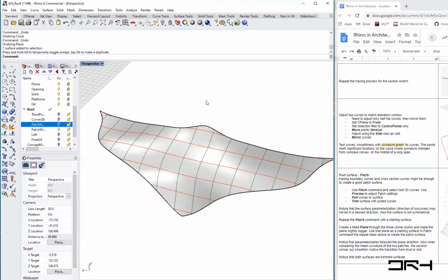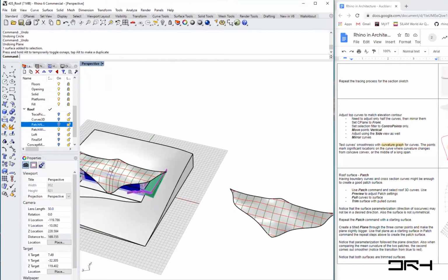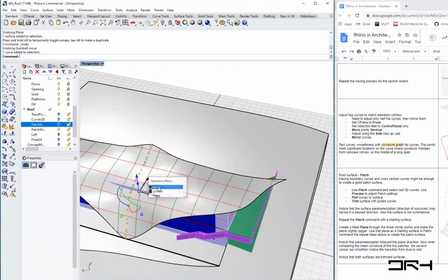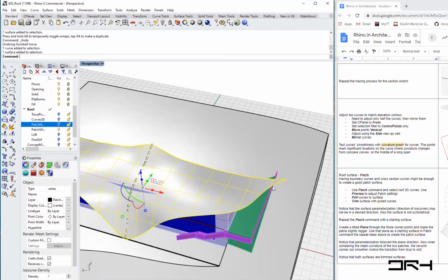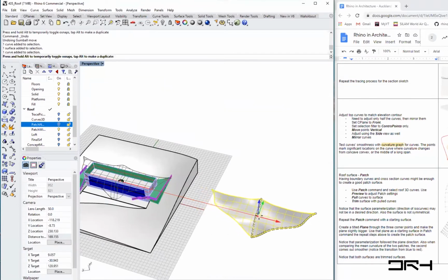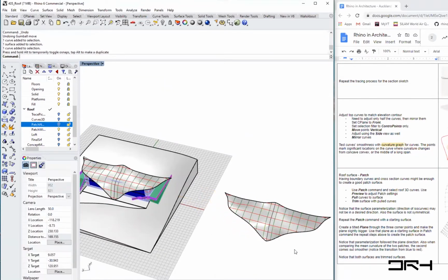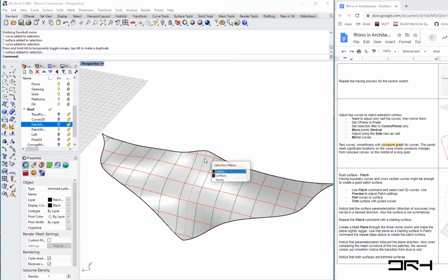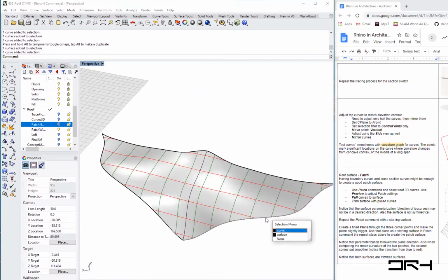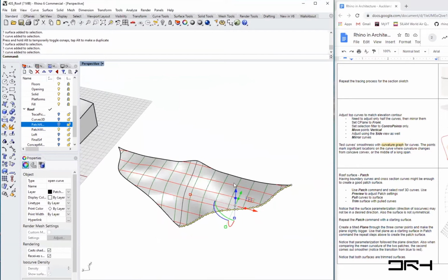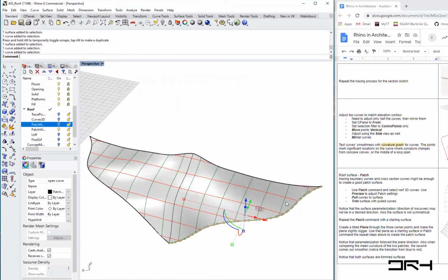So there are some very important curves here that we use. Before I do that, let me just pick the curves as well. Curve 1, 2. Is there any side curve? Yes. So I'll just copy all those to the side. So now I have my surface, I have that curve, and I have also another curve to the side. All right. So how can I create the loft curves?